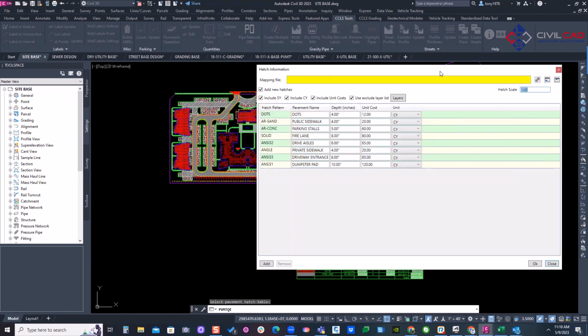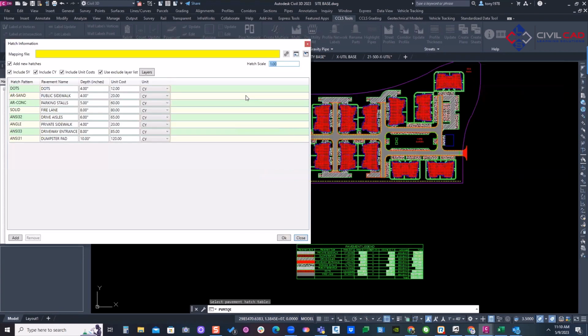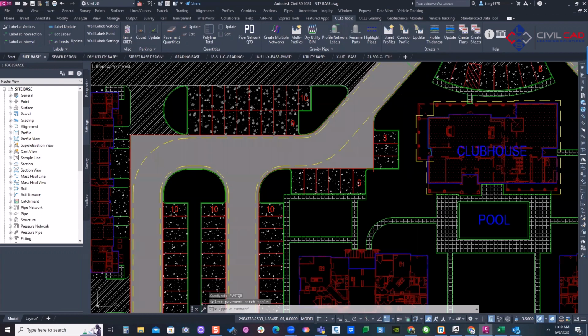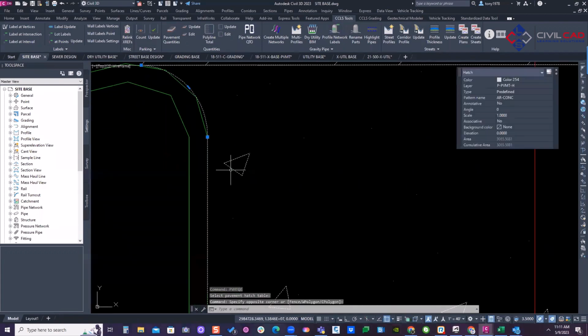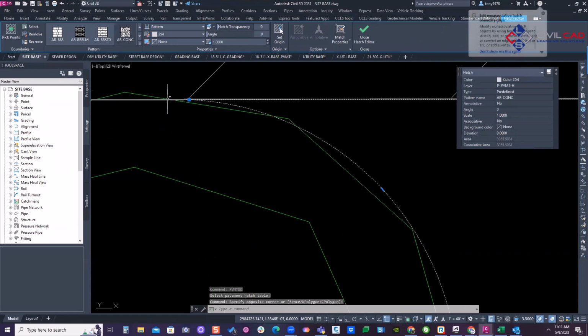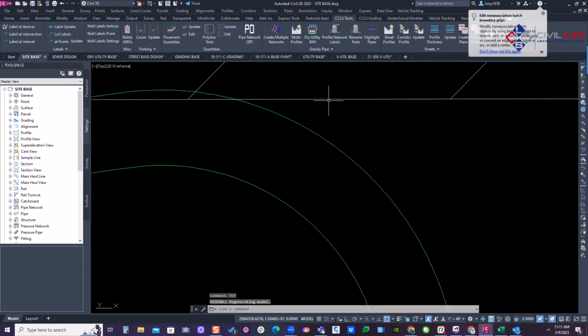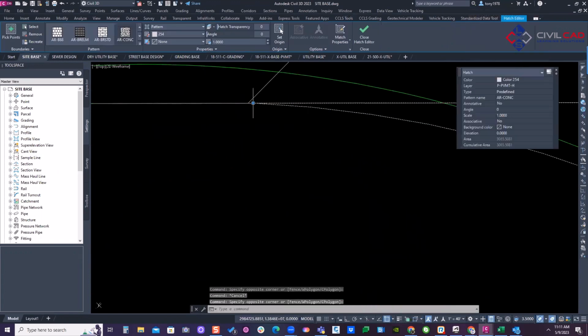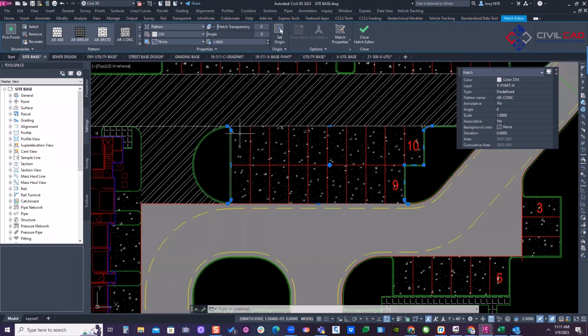And also the scale of the hatch based on the legend, you can actually change the scale of the hatch up here. Now, if any hatch is not quite closed, maybe you have some overlapping lines that cross, you'll get an error message up here that tells you to zoom in and fix that. Well, that typically happens around sharp little corners, maybe like this. And where this little hatch continues on, let me hit regen real quick. This is where it typically happens. Click on that hatch. The line here will overlap, and sometimes I'll just take that grip and slide it back, and you'll see that error message disappear in order to get the quantities.